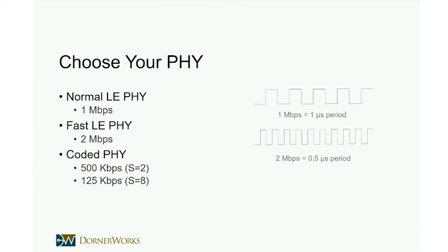If you want 2 times as fast, then you're not going to get the added range that Bluetooth 5 has advertised. So it's important to note context to that. Bluetooth 5 really tried to give you options to match a bunch of use cases. Some use cases said, hey, I want to advertise a bunch of data, and I have all these beacons all over the place, and I want to beacon from 100 meters away. And Bluetooth said, great, we'll add something for that.